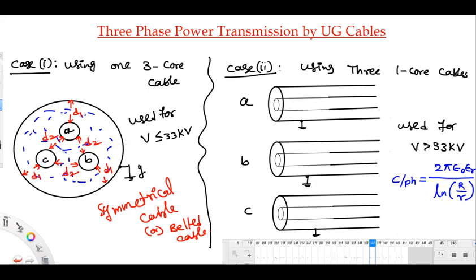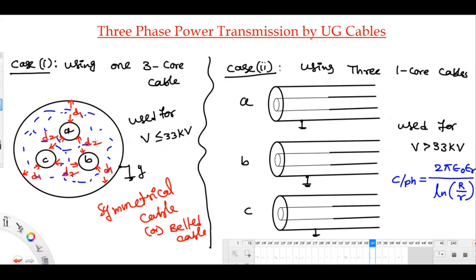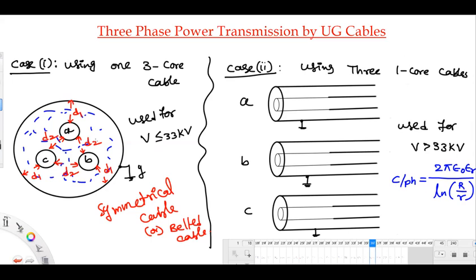And sir, why did we calculate insulation resistance for HVDC? Why not for AC? AC also will give the same number. Why I have shown DC is to show that circuit. To tell you simply, insulation resistance is in parallel for that purpose. So the cable will have resistance and capacitance only. Inductance value will be 0.